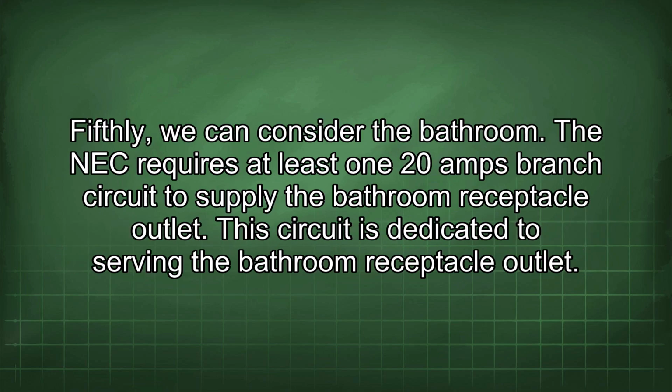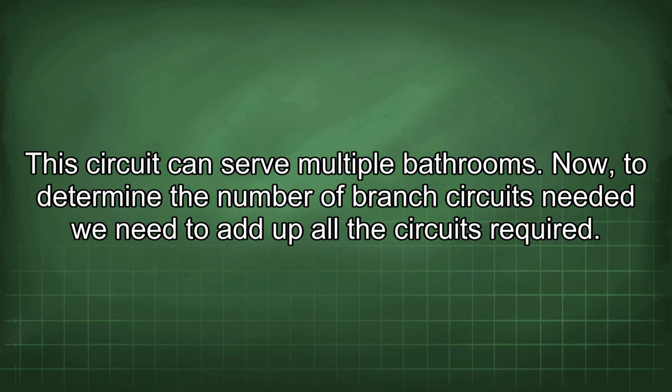Fifthly, we can consider the bathroom. The NEC requires at least one 20 amp branch circuit to supply the bathroom receptacle outlet. This circuit is dedicated to serving the bathroom receptacle outlet. This circuit can serve multiple bathrooms.